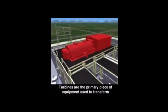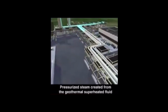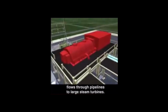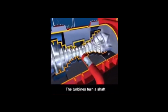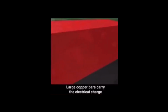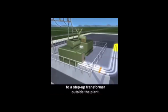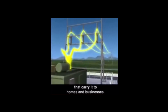Turbines are the primary piece of equipment used to transform geothermal energy into mechanical energy. Pressurized steam created from the geothermal superheated fluid flows through pipelines to large steam turbines. The force and energy in the steam is used to spin the turbine blades. The turbine turns a shaft, directly connected to an electrical generator. An electrical charge is created when magnets rotate within the generator. Large copper bars carry the electrical charge to a step-up transformer outside the plant. Within the transformer, the voltage is increased before the power is sent to the power lines that carry it to